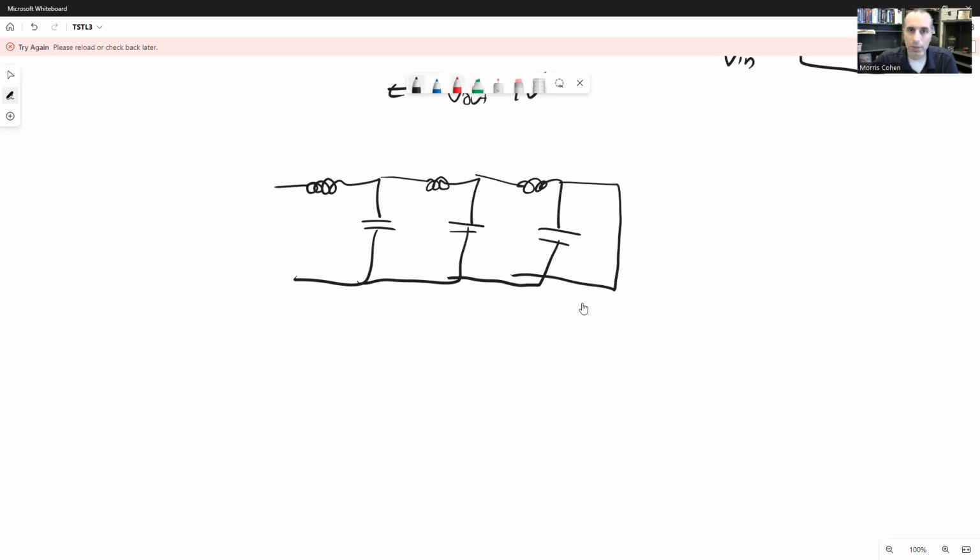So what's going to happen in this case is we've got current that's going to run through right here, right? That last voltage right here, right? Vn equals 1 is established on this node, and we have a current here that's established. Now, ordinarily, this current would come and flow through this capacitor and charge it up. But in this case, it can't because the capacitor is short-circuited. So the capacitor is not allowed to have any voltage on it, which means the current here is not going to flow through the capacitor, because if we put current through a capacitor, we must be changing its voltage. And changing the voltage of the capacitor is not allowed because it's connected to a short circuit.